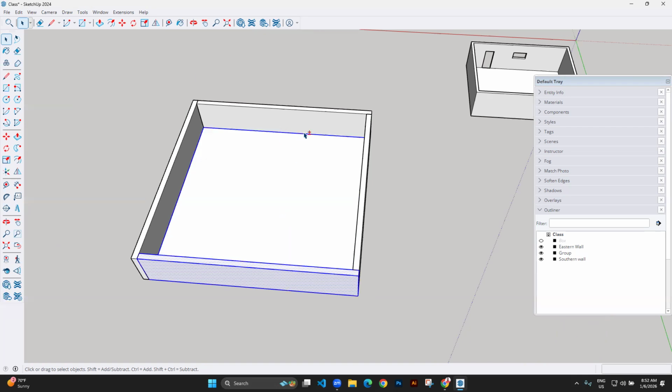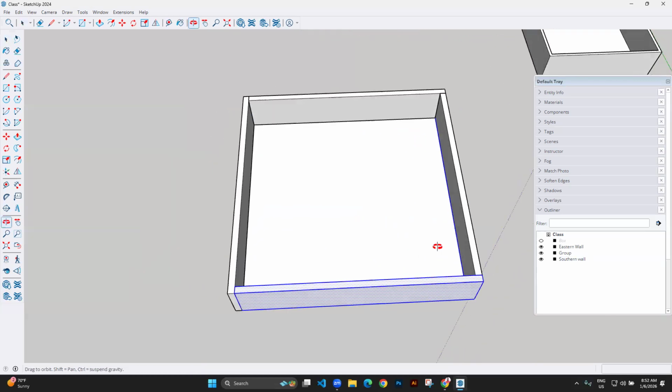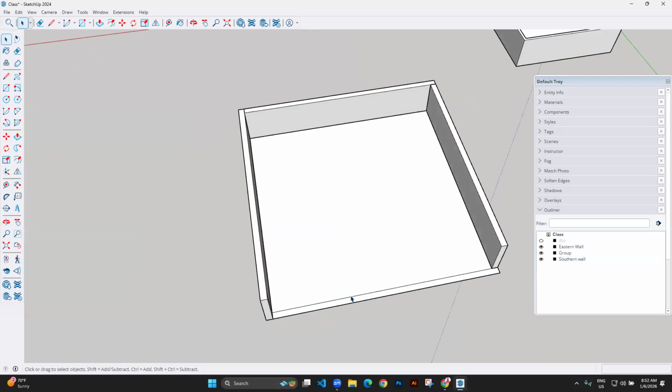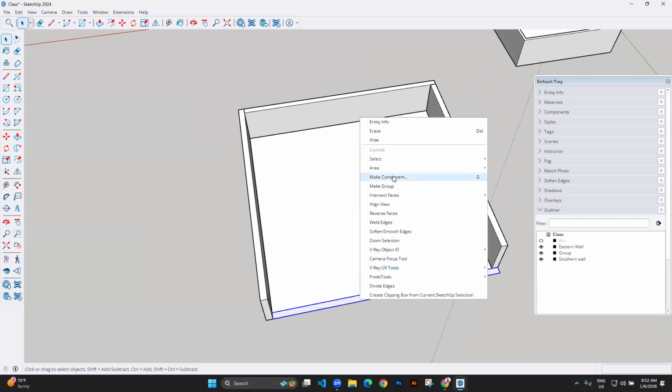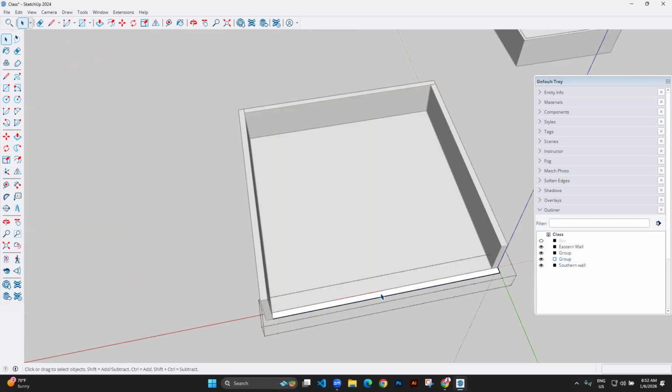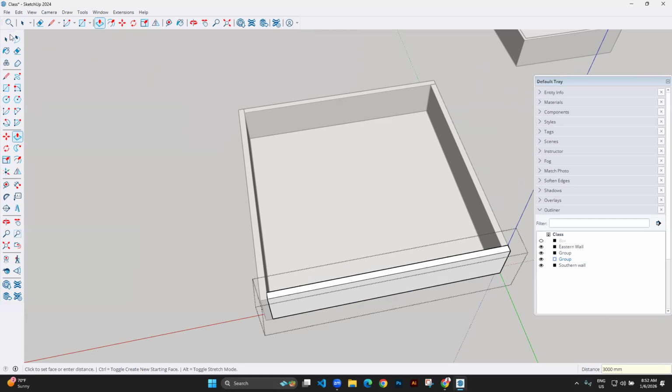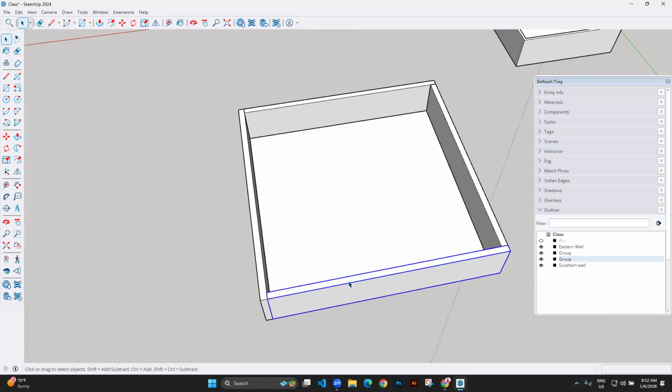I reduce this edge. And you see now, it starts even clicking other things. Like it becomes very hard. And you may end up forgetting some of them. So see that is bringing more work. But as simple as we could do, just right click, make a group, then edit. You start editing when you've already created that group. Then now this is very perfect.